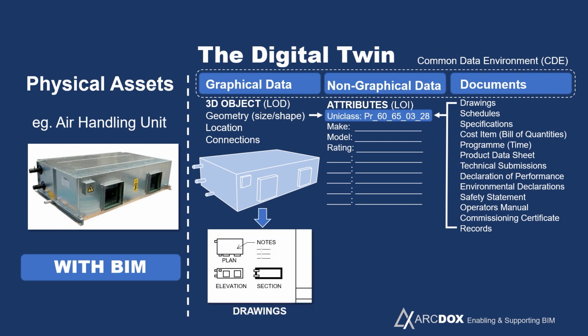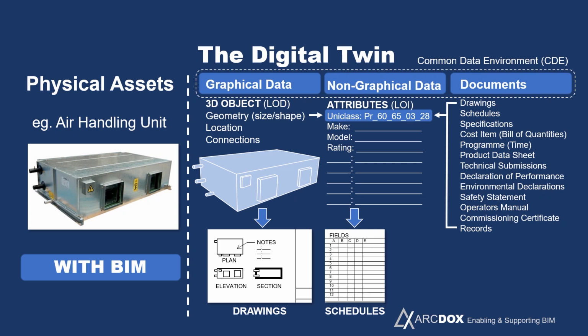If you've used BIM correctly, then you can still have drawings, but nobody has to draft those drawings. So there's enough geometry within the object to generate the drawings. There's also enough non-graphical data within the attributes or properties of that object to generate any notes on drawings. So nobody has to type the notes on the drawings. Nobody has to type out schedules anymore, because there's enough information within the non-graphical data to generate any type of schedule you might like to use. So drawings and schedules are really just outputs that people may want at times from the data.